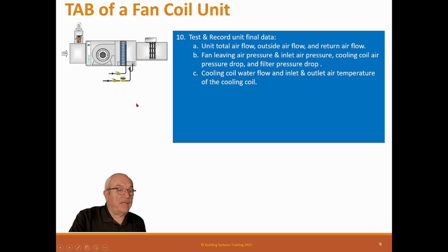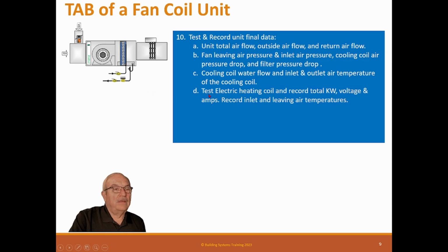Well, the reason that data doesn't matter is because you can't set the load in the building. It is whatever it is. You could bring in a heater and heat up the space to design flow, but that's a whole lot of work, and that's not in your scope to do. So temperatures to me were just to show that the cooling coil is actually working. It's doing something. How much it's doing is not critical.